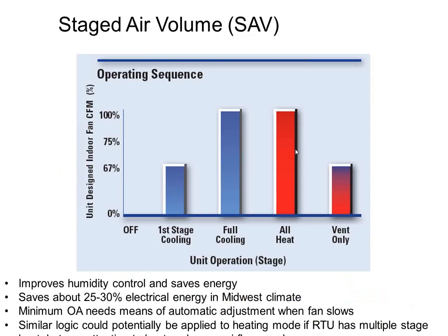So like I said, we run reduced airflow when we go into vent-only mode or one-stage cooling mode. Now, someday we'll want to do this on the heating side as well, but we have to do some things to make that happen with the economizer guys. There's also some concerns about cutting airflow back on heat exchangers for gas-fired heat because we're already providing too little airflow in many cases with too high of discharge air, but that's a whole other discussion for another time. The good news, as we talked about last week, vent mode is like 60% of the hours. We already kind of established that. So if I'm cutting your airflow back for vent mode, that's really where the big savings is at. The fact that I get to cut it back for first stage of cooling also is kind of a bonus, and really it's a dehumidification bonus.